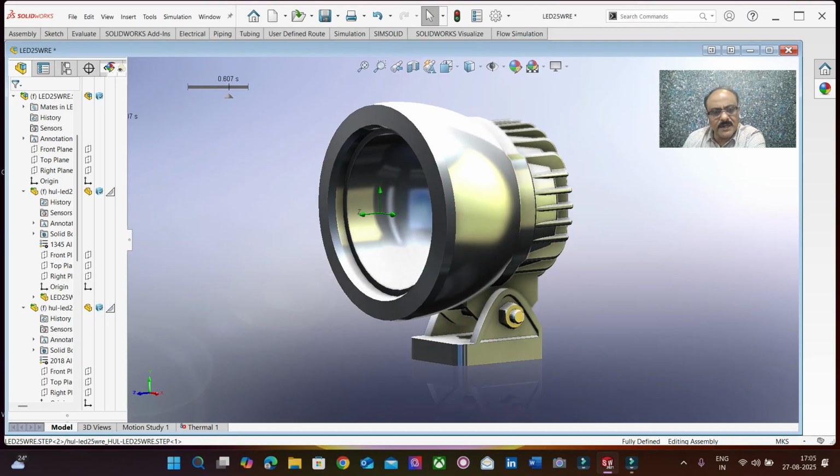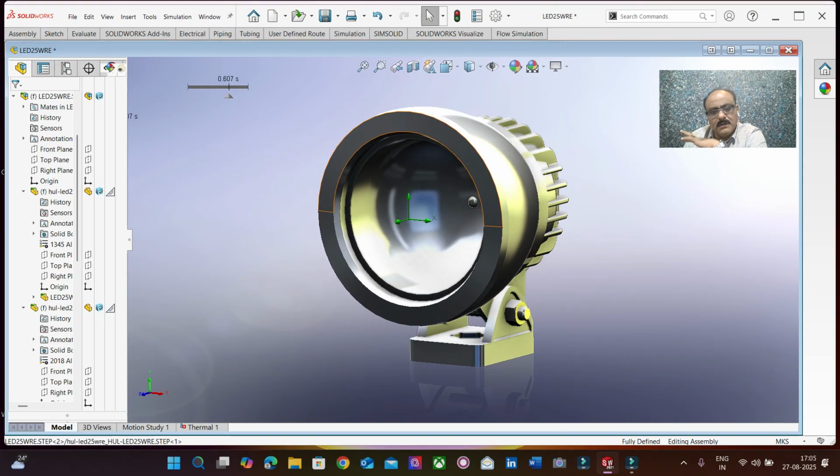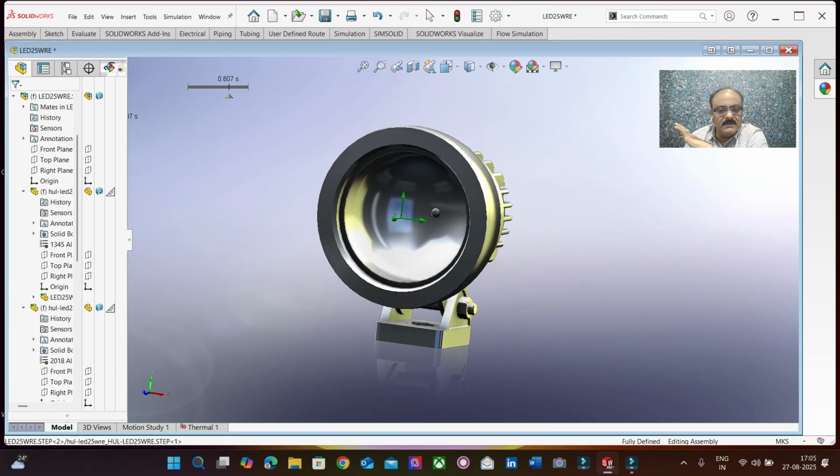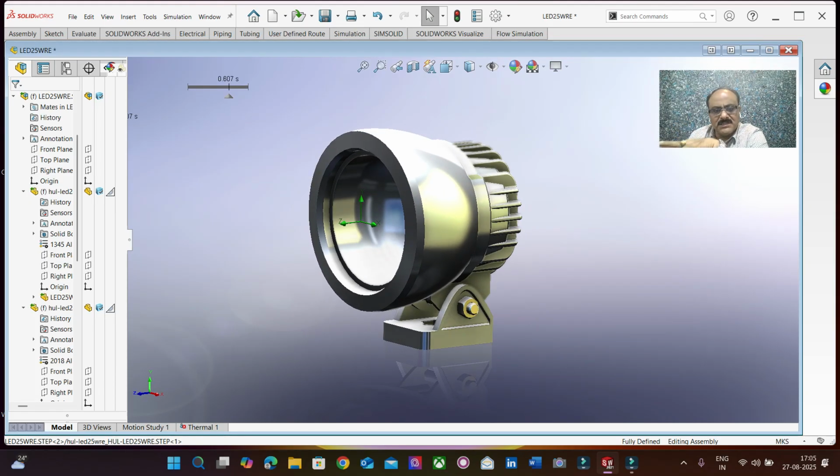Now, what we are trying to do is define the computational domain. The domain is nothing but the particular region of computation. So, was this an internal aerodynamics? Say, assuming that the system itself has a cooling process, the fan, or some external convecting source to remove the temperature, and that is integrated or embedded within this particular projector lamp, then that becomes an internal aerodynamics.